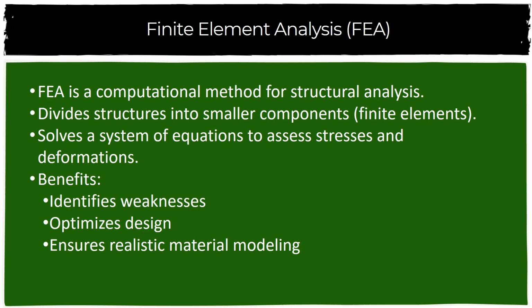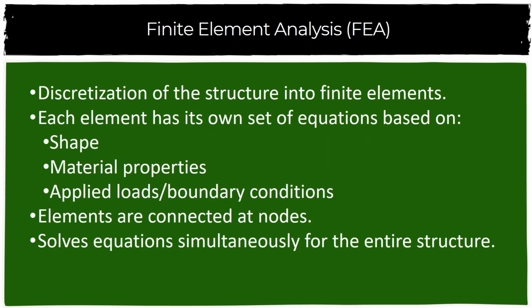Ensures realistic material modeling. Discretization of the structure into finite elements. Each element has its own set of equations based on shape, material properties, applied loads, boundary conditions. Elements are connected at nodes. Solves equations simultaneously for the entire structure.